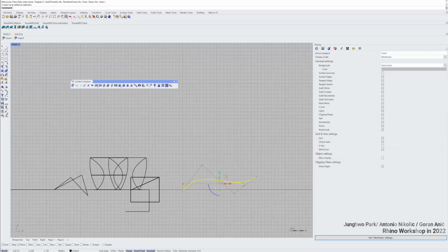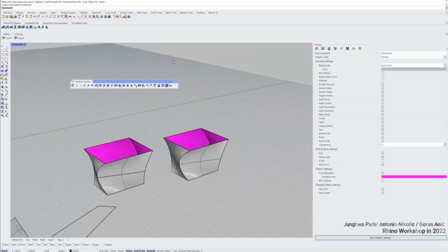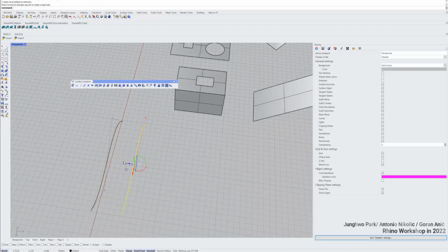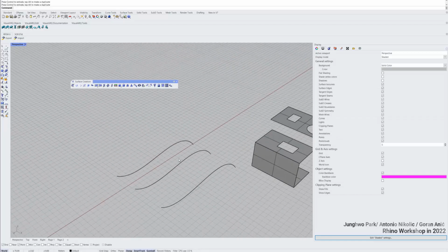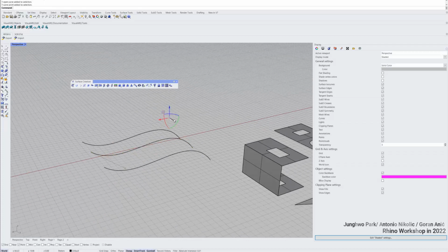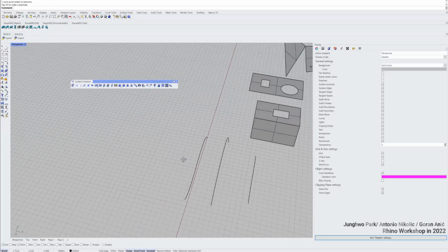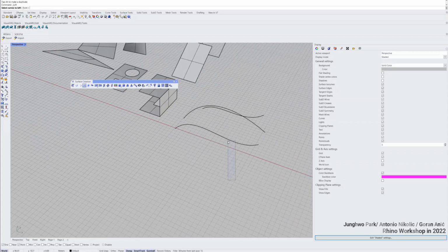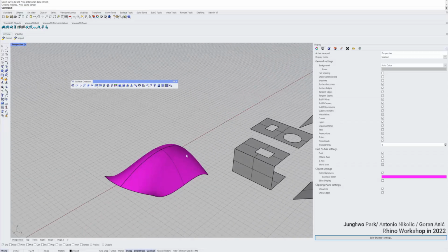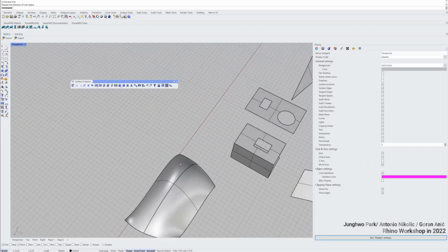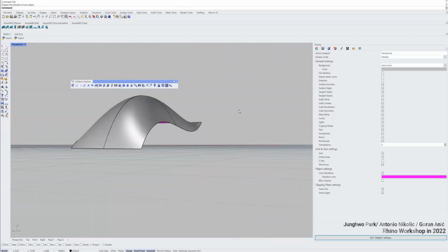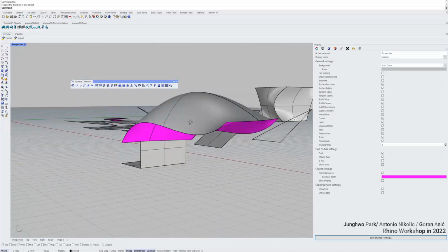surface. So I draw one curve line from front, and from the perspective I'm gonna copy a couple of them, and maybe this one I will change the control point a bit, like differently. Here also, maybe I'll scale it eventually here a bit and move it a bit down. And now if I loft the 3 of them, we get the surface, and the direction is opposite, so I flip it. That's how you can create surface with the lofting tool.